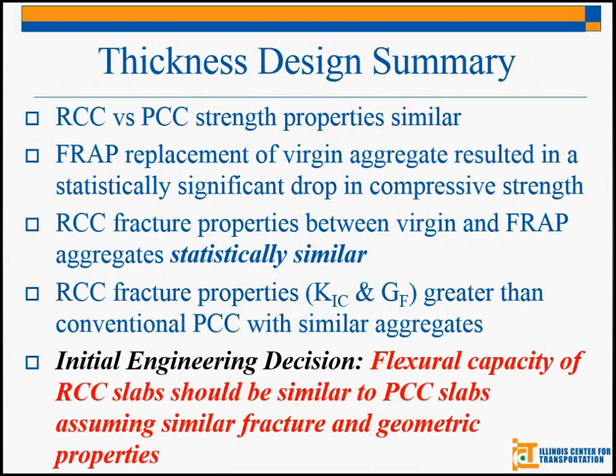So the summary of that first study is that RCC and PCC have, or can have, similar strength properties, and can have similar performance. And so it's important that when we are designing RCC pavements, we look at the actual properties and consider them in our design. The important thing to highlight down here is what I've already talked about: if the mixes have similar properties, then they should behave well in the field, and there shouldn't be any reason to have a thicker RCC pavement.